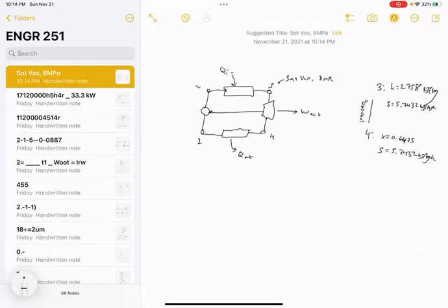So now what we're going to try to do is find a mixture from the mixture tables which has exactly this value of entropy at 64.75 quality. So how are we going to do that? Well, it would be pretty difficult to just start looking through every single line and checking what the entropy is at 64.75 quality until we get something. We obviously don't have the time. Maybe there's some other bit of information we can use to narrow our search down.